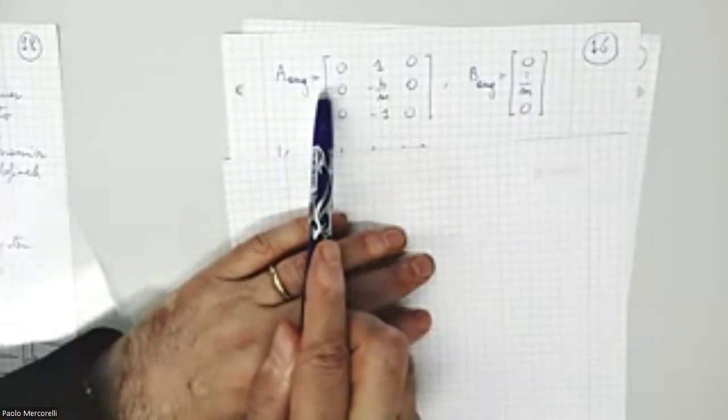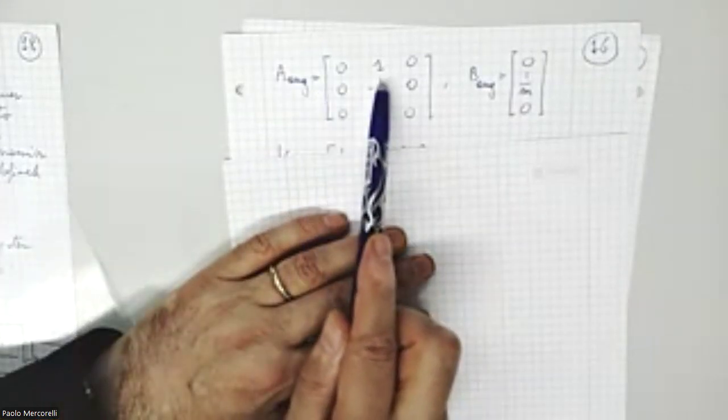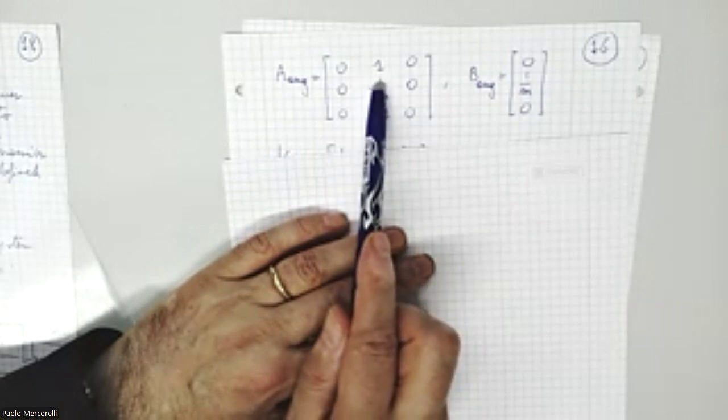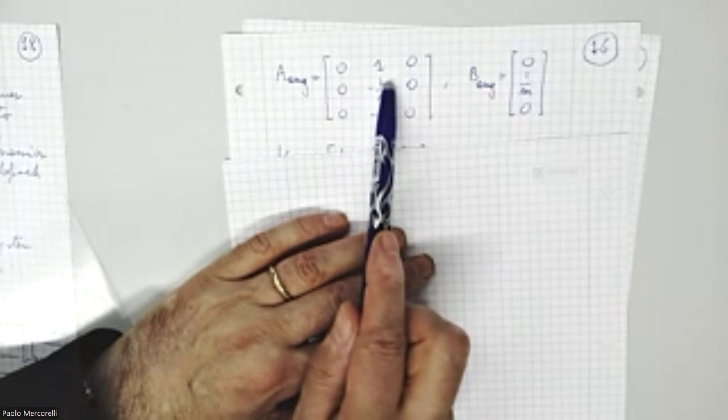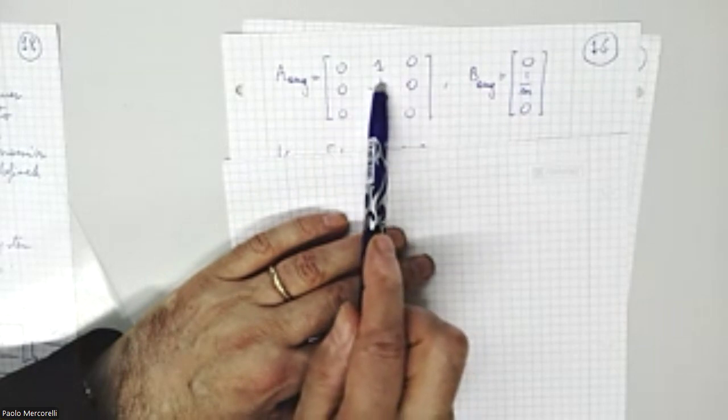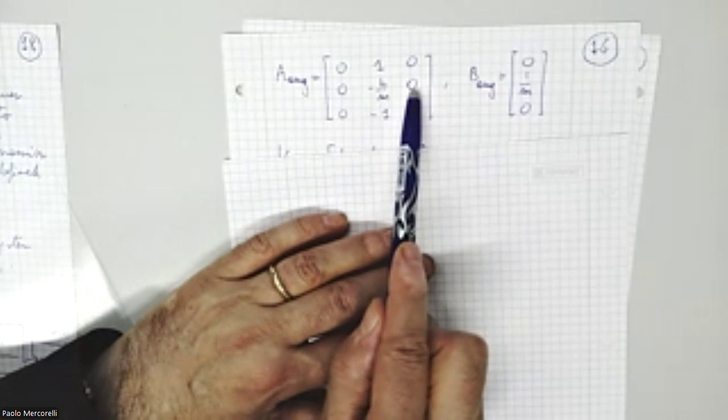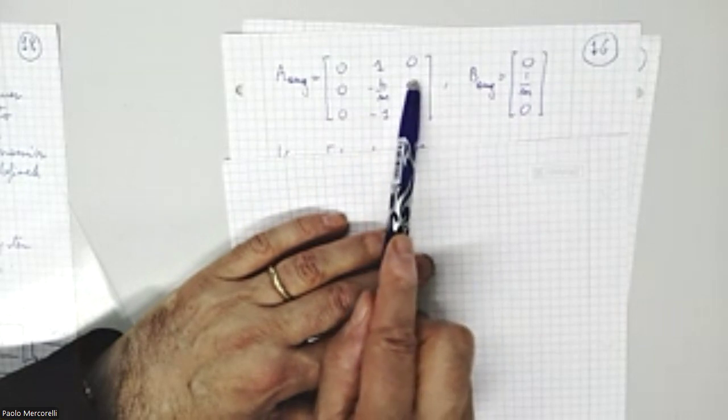If I put K11, K12, Ki equal to 0 here in A extended in order to calculate A augmented, I will obtain this expression. K11 is 0, so I have a 0 here. Here in the numerator, I had minus B minus K12 divided by M. If K12 equals 0, there remains B divided by M. Here, I had minus Ke divided by M. This means I have a 0.